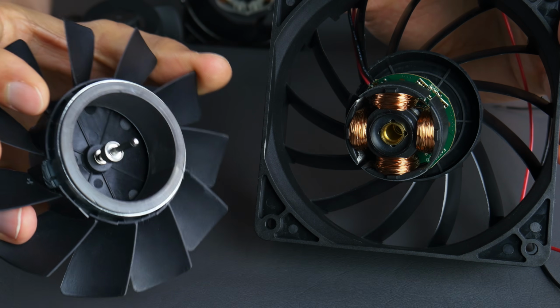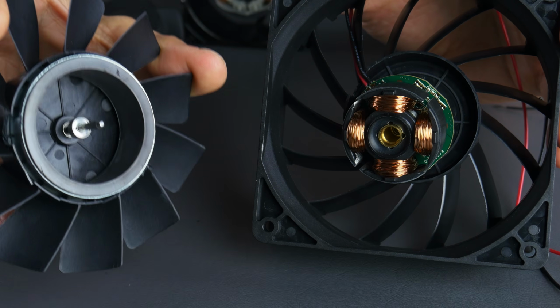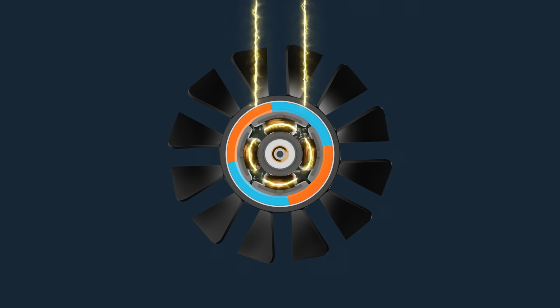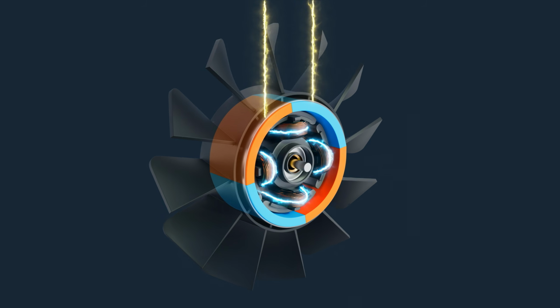Finally, there are EC, or electronically commutated motors. These are interesting because they are essentially a brushless DC motor with more controls around them and the ability to provide them with AC power instead of DC power. So thinking back on the brushless DC motors we just discussed, all of the physics principles of how they work are still there. But now, the EC motor can accept AC power, internally rectify it, and use the resulting DC to drive the motor, meaning these can be a drop-in replacement for AC motors.